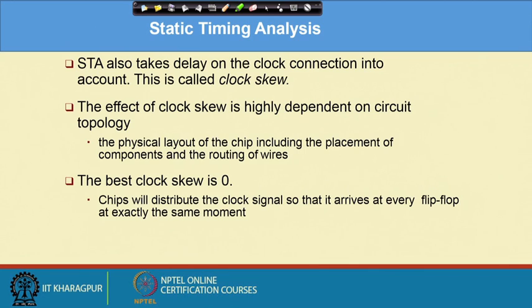And clock skew is an important factor, not only clock skew, but also setup time, clock to Q, and T logic. During optimization, what we have done till now for the combinatorial logic part is reduction of timing or reduction of area on those particular paths, but we have not considered the other things which are associated in the whole timing closure calculation. That we will see in continuation of these lectures.